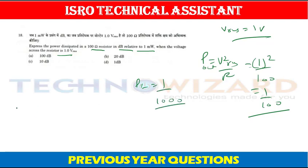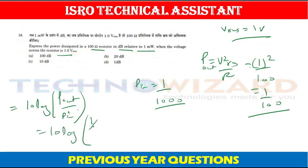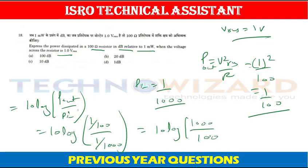Okay. Now we have to find the power in decibel. Then 10 log P output upon P input. This is equal to 10 log power output 1 upon 100 upon 1 upon 1000. Okay. This will be equal to 10 log 1000 upon 100. Therefore, 10 log 10 and log 10 is 1. Therefore, 10 decibel is the answer. Power in dB will be 10 decibel. Option C is the correct answer.